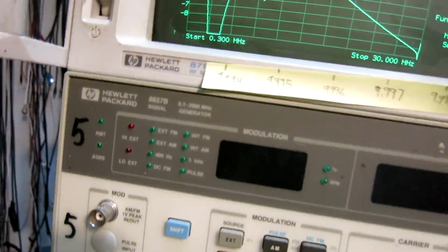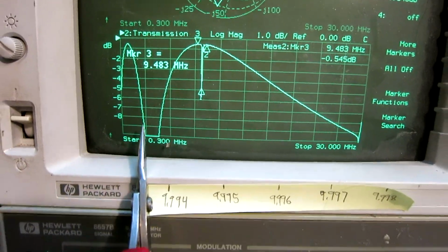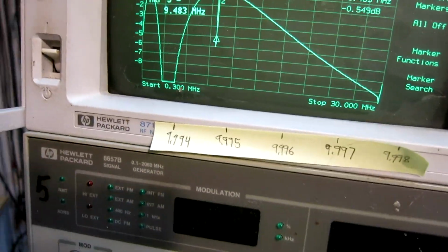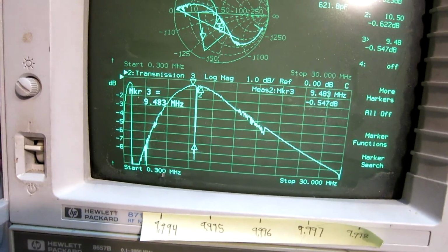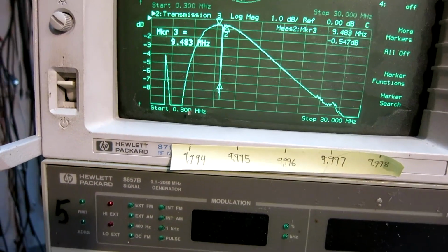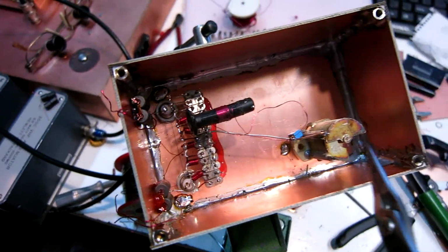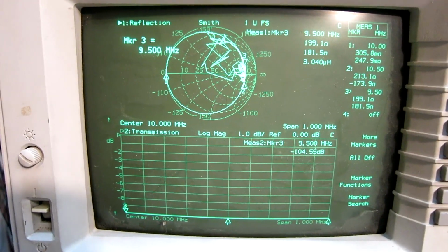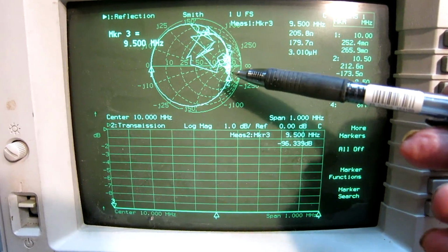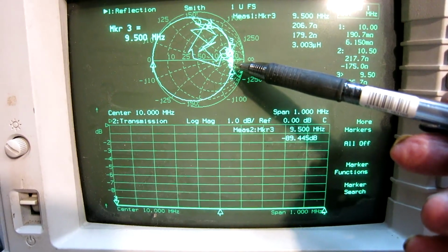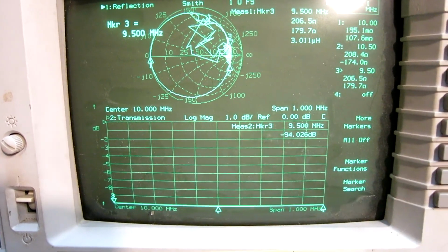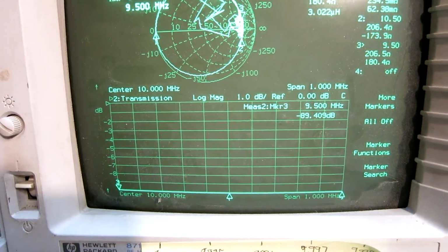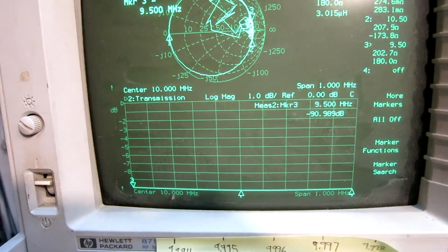And there is a resonance here, fairly deep one, and it affects performance several megahertz below the frequency of interest. The origin of that, I short the capacitor to ground, and then you can see it disappears. So this coil is a series resonator with the capacitor, but it doesn't matter. I fine-tuned the inductor for the impedance at plus minus half a megahertz, that is half a megahertz above and half a megahertz below the resonance on 10 megahertz to be symmetric. So it's inductive on one side and capacitive on the other. And that is without a cable connected on the output from the notch.